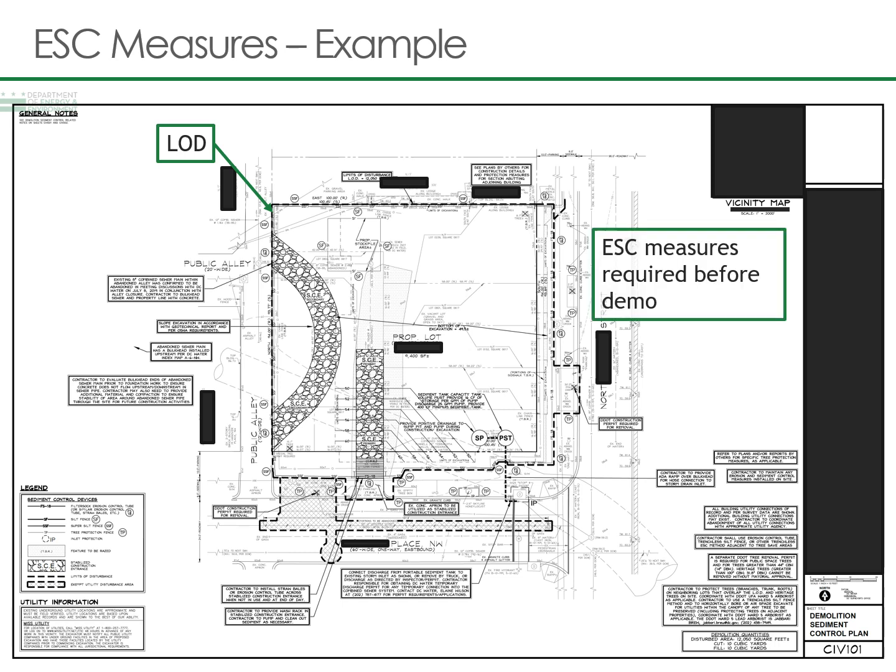It's important to remember that erosion and sediment control measures must be in place before demolition happens. So in this case, this designer has included a separate demo ESC plan and developed a sheet where this phase of the construction has its own separate ESC plan.